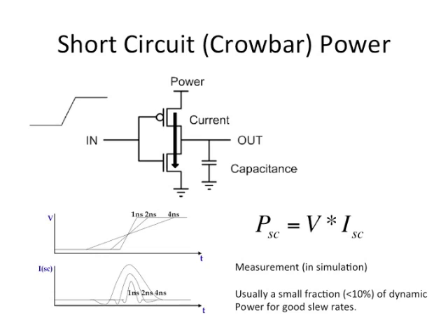Maybe because the capacitance will take some current: as the input is increasing, the output will start decreasing, so there will be some current through the capacitor. That's right. Some current will flow through the NMOS and some current will flow through the capacitance. What is being plotted is the total current drawn from the power supply. So if the input ramp is faster, the voltage at the output will also start decreasing at a faster rate, so the current through the capacitance will be more.